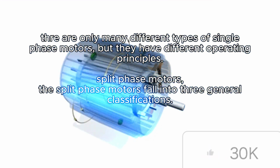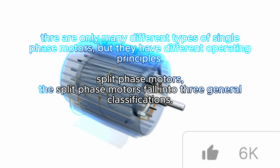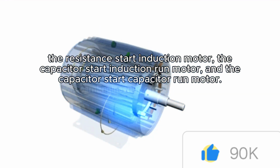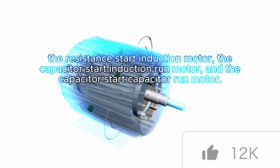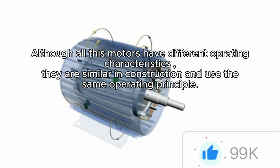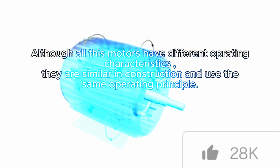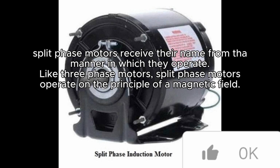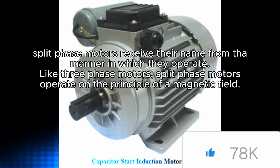Split-phase motors. The split-phase motors fall into three general classifications: the resistance start induction run motor, the capacitor start induction run motor, and the capacitor start capacitor run motor. Although all these motors have different operating characteristics, they are similar in construction and use the same operating principle. Split-phase motors receive their name from the manner in which they operate.